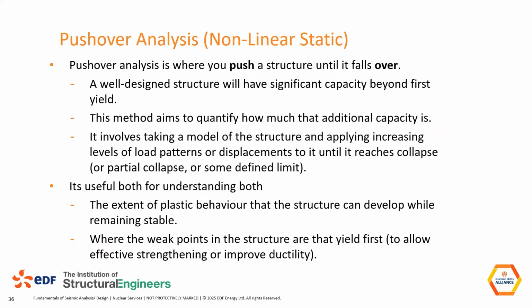We have a pushover analysis. Essentially, you apply a set of loads to a structure, a load pattern. You define a load pattern representing a particular event, say an earthquake, and you incrementally increase or prorate those loads until eventually the structure falls over. And what we're doing here is going beyond yield. So if you want an elastic design, you hit yield, you stop. That's the capacity of the structure. Pushover, hit yield, you keep going.